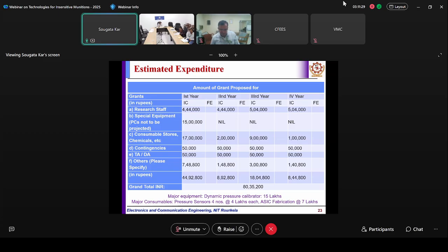Yeah, sir, in this IEPE sensor, the conditioning is inside the sensor. So that's why it is giving the voltage. The sensor has its own conditioning inside, so we need only to give power to that signal conditioner sensor. Sir, those sensors have inbuilt electronics, but if we want to build the electronics ourselves, that can also be done, sir.